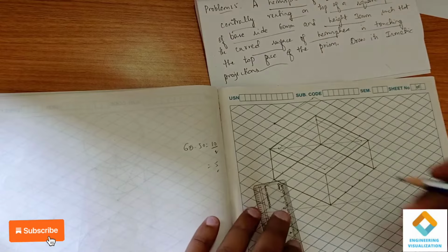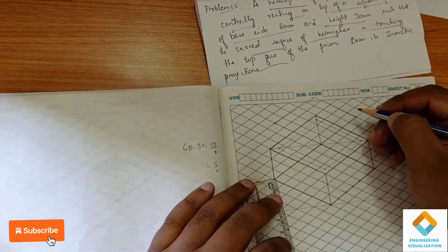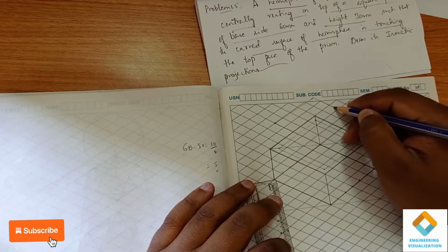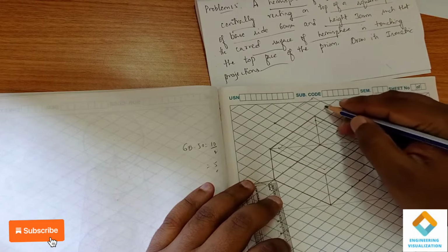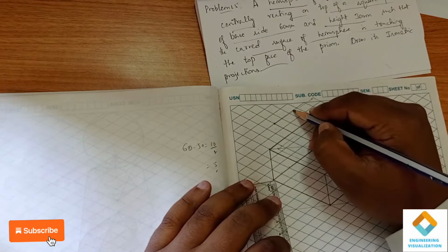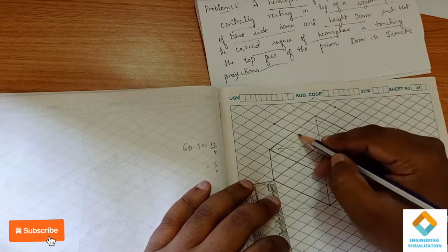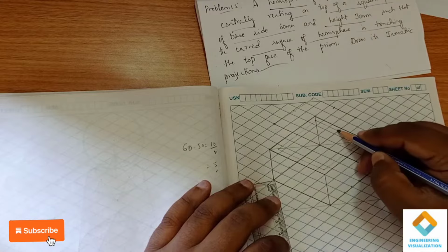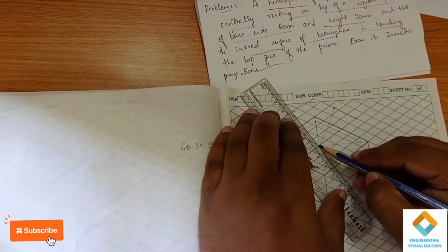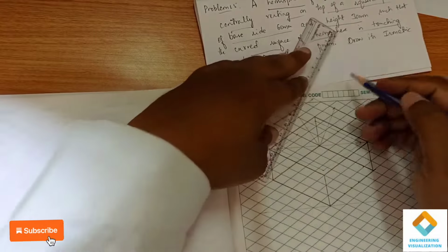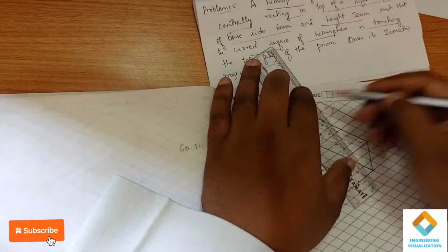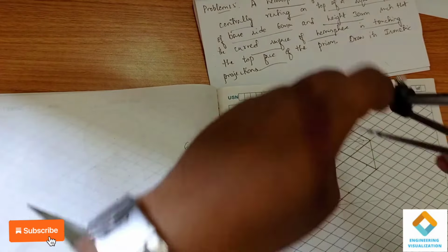After constructing it, again for the four-center method, marking the middle points. So 5 means 20, 1, 2, 3, 4, 5. So 25 means here, exactly 25. So construct the ellipse here.